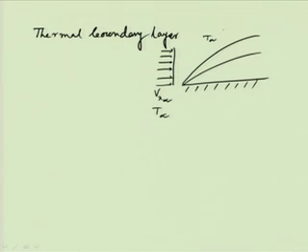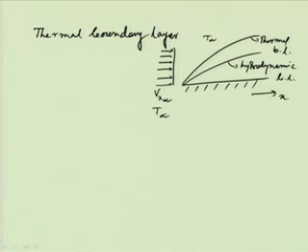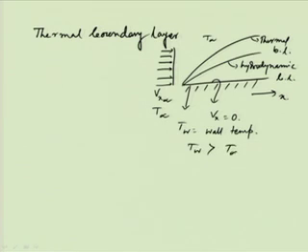And we can say suppose this is a thermal boundary layer, and this I will say is the hydrodynamic boundary layer. Now, the question is, here it is along the x direction, and at this point velocity Vx equals 0, and we will say that Tw is the wall temperature, and we can say that Tw is greater than T infinity. So, heat is being transported from the wall to the fluid.